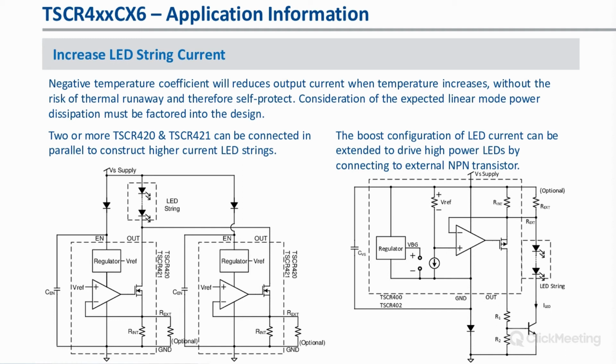And here you see on the left-hand side, on the low side control, that you can actually increase the current by paralleling devices. The best way to think about the advantages of this CMOS version is to imagine 304. We showed the 55 milliamp graph through slides before this. It is actually to think 304 LED strings in parallel. Of course, in the CMOS version, they are going to be much better matched than in the bipolar version. So you're not going to see any differences in brightness between the LED strings.